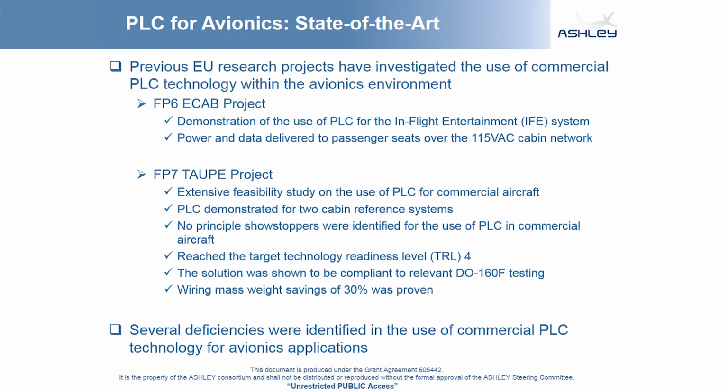However, as with other technologies, certain deficiencies were identified in the application of commercial PLC technology to the avionics environment. Commercial PLC technology has been developed for consumer in-home networking applications, which makes certain aspects of the technology not suitable for more real-time applications. Unfortunately, the relatively small avionics market size compared to the consumer market leads to unattractive conditions for the commercial technology suppliers, and therefore there is a general lack of support for providing an optimized solution for avionics systems.